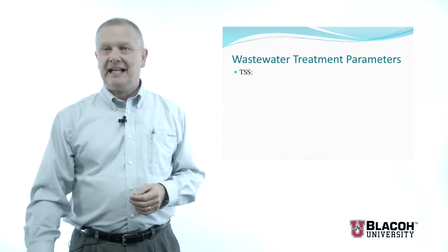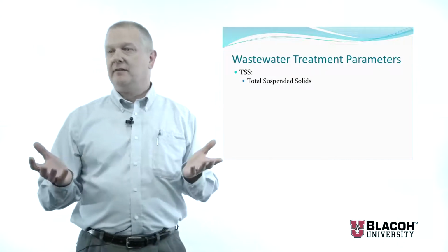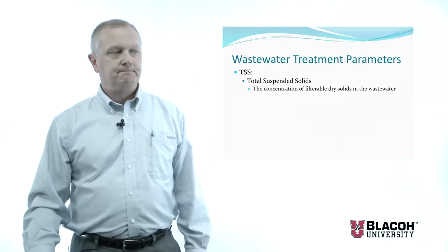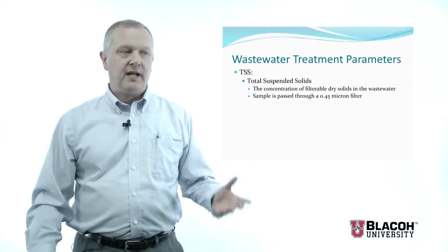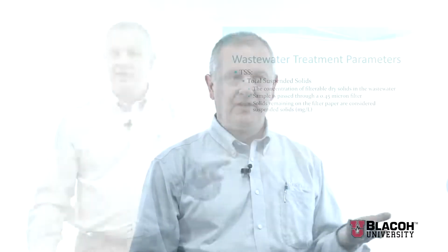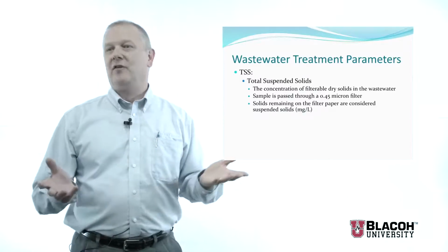Let's move on to TSS, or total suspended solids. This is a measure of the particulate matter in the wastewater. What we do is we run the wastewater sample through a 0.45 micron filter in a standard procedure, and whatever stays on the filter paper is considered suspended solids. Obviously there are some very, very fine solids that do go through, but we consider those dissolved because they're so small that essentially they are. You dry the solids on that filter paper, weigh it, and now you have the suspended solids concentration for that wastewater.